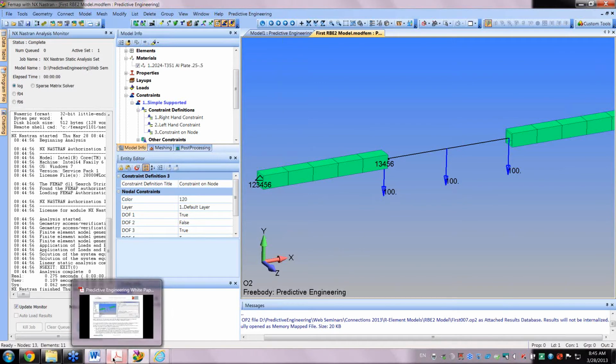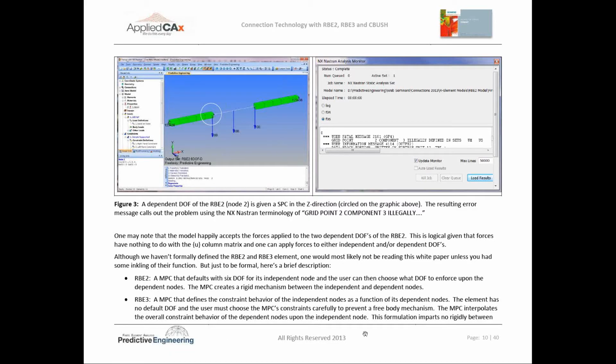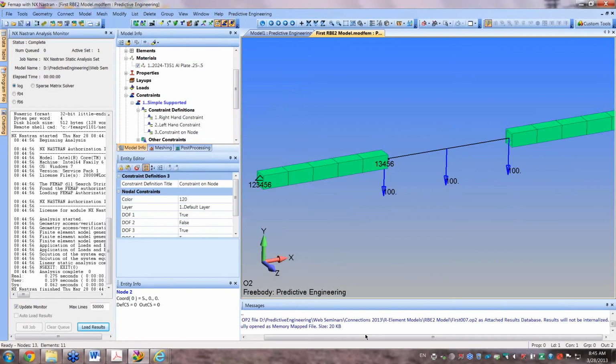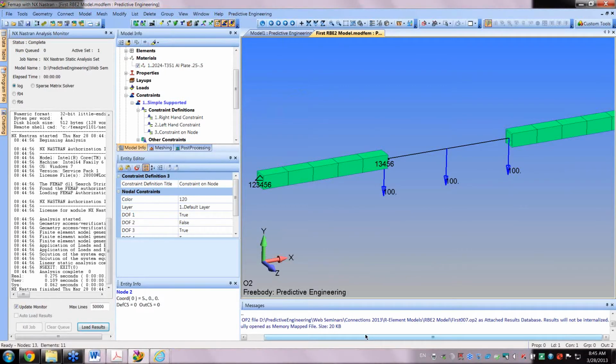What do you think, Adrian? Have I belabored this point? I don't want to belabor things. I want to just, you know, get it. That sums it up. It's our, what did we call it yesterday, the double dipping. Yeah, that's like it. If it's on RBE2 and you're using the DOF2, then don't constrain it with DOF2 because it's going to have a problem. Yeah. Don't double dip. But at the same time, know what you know.